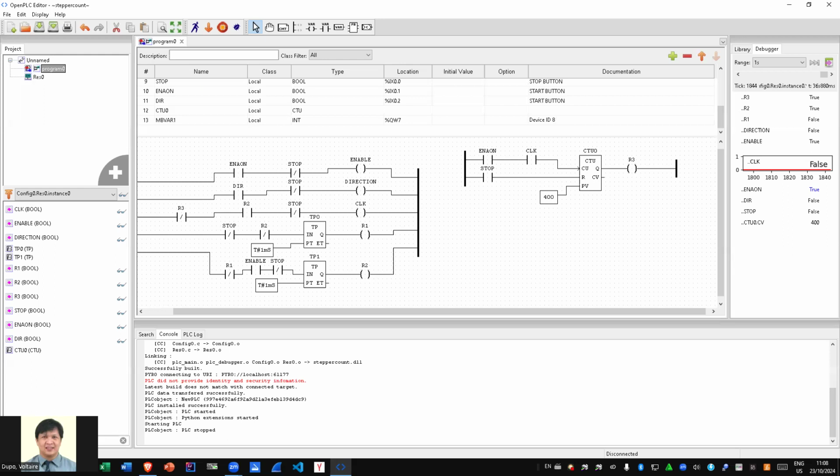So in terms of Modbus addressing, this should be 327 or so, base 0, not base 1. So this is still a 7, when we try to do the Modbus connection towards the device. So the next problem is we need to supply an initial value to it. Let's say 2.